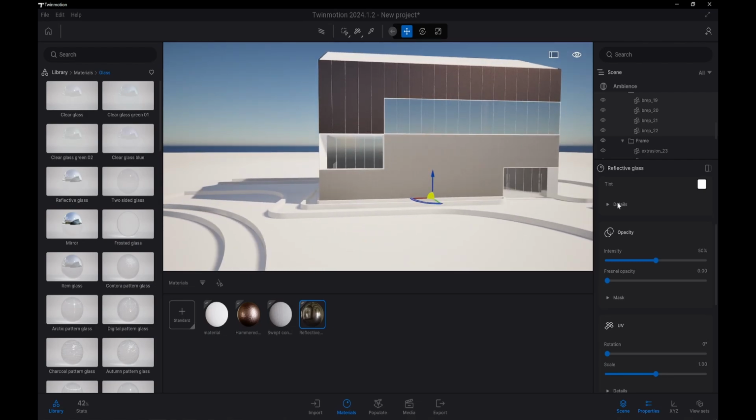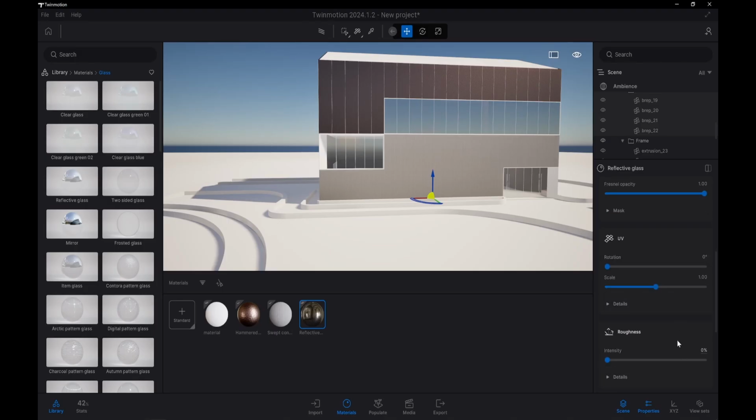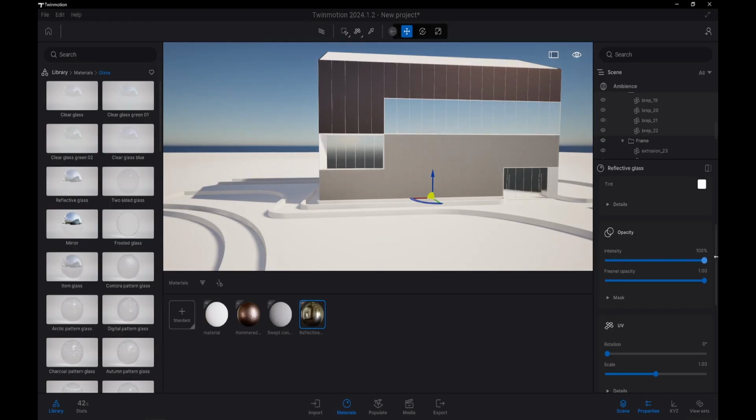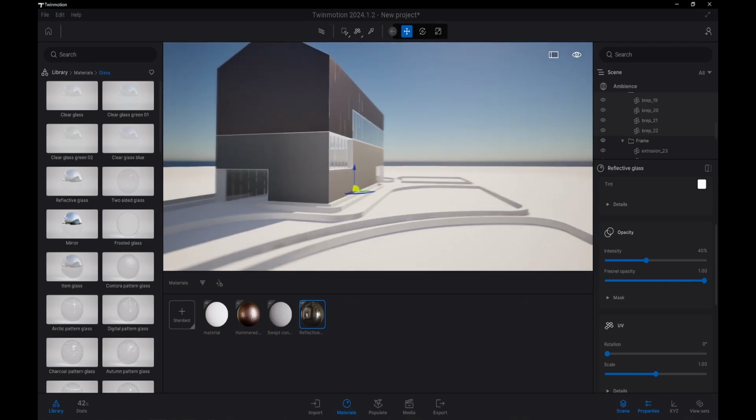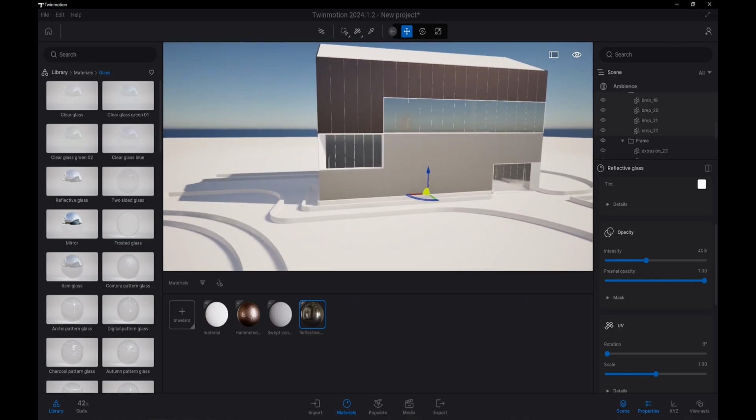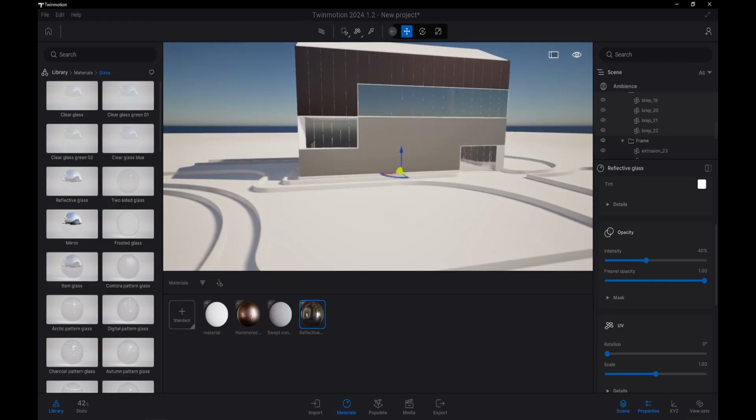And I can change this, right? So like I can change the opacity. Maybe I want it a little bit more opaque. Don't worry too much about the Fresnels, but what's important is, I don't want 100% opaque because then it's going to be super reflective. I want it a little bit less than 45, just to get some depth in there. And don't worry, we'll get to the lighting and things like that. Vegetation. I think everything else is fine here.